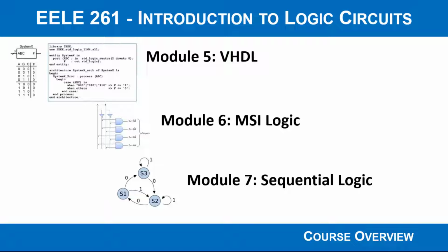So we've invented this thing called a hardware description language, which is a programming language that allows us to describe the functionality of a logic circuit. And that's really cool because we can describe it using text, meaning that we can describe very large systems using just alphanumeric characters. In addition to, since we're describing the functionality on a computer, we can actually perform simulations of the description in order to verify that it's accurate.